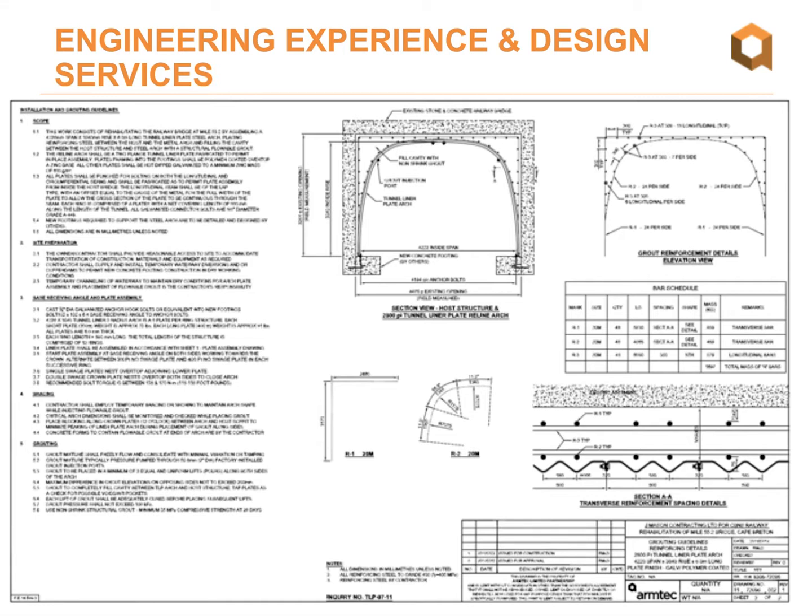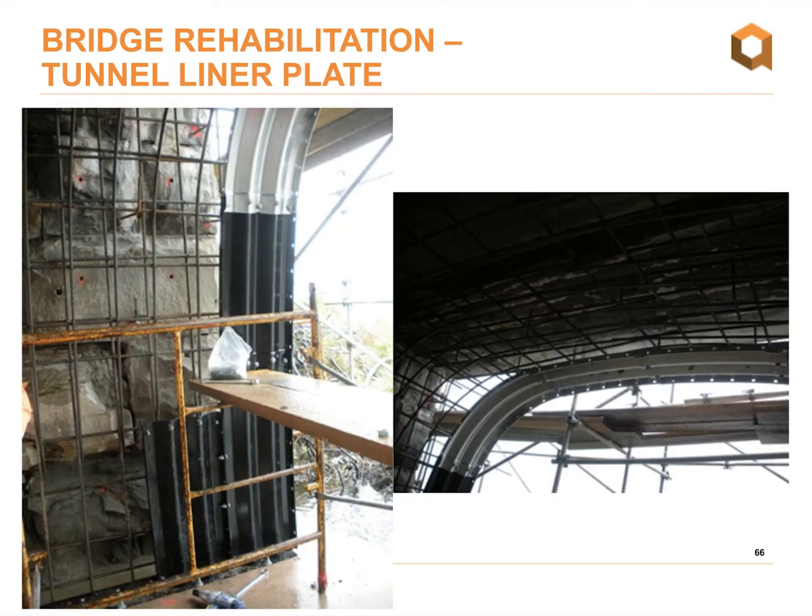So a tunnel liner plate was again selected, and a set of drawings were produced for the owner's consideration. For this railway application, we recommended a reinforced structural concrete grout. As you will see on following slides, our StrataCat coating was applied to the footing plates as the brackish water of the Bras d'Or Lakes warranted extra protection from the elements.